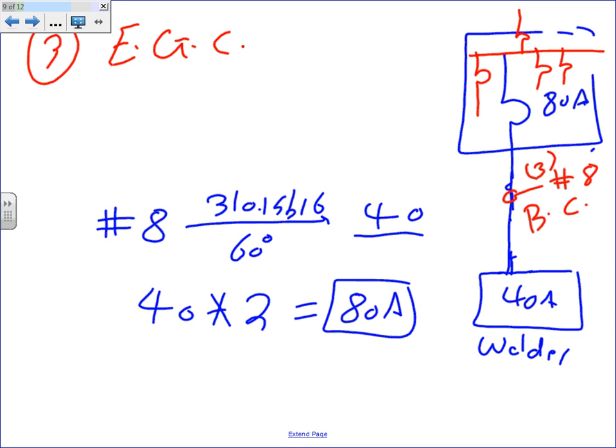What you're saying is, here's the trip curve of one circuit breaker, and I can have another trip curve of the same circuit breaker that's completely different. Yes, you can play with the settings of the trip curves. I don't want to go there this time. Yes, you can tweak it to make one trip before the other, especially on short circuit.